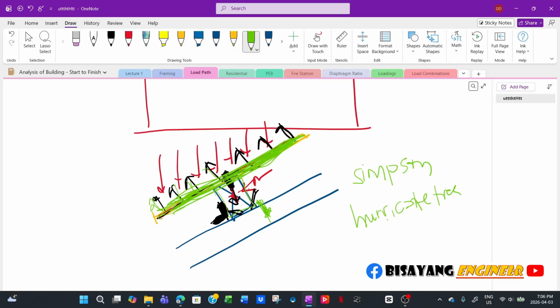For example, you space your purlins at 6 feet on center, and then you design the purlins based on the stability, but the roof cladding is not sufficient to carry that much weight. So all you have to do first is determine what's the maximum span you can have for the roof sheeting, your roof cladding, for that specific loading.